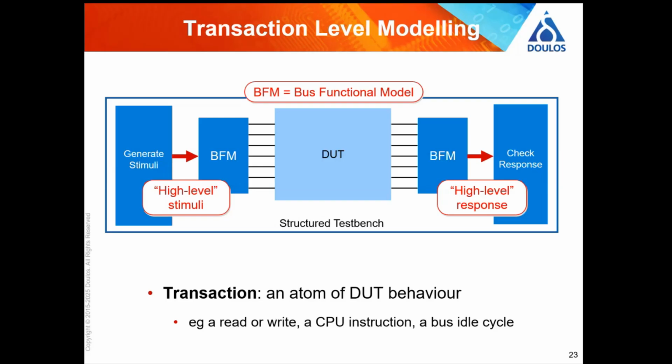And that thing is often generically called a BFM, a bus functional model. And there are different kinds, and I like the terms driver and monitor. So the one on the left of this diagram, you might call a driver. It's translating the abstract transaction, the concept of a write and a read, to the actual ones and zeros that does a write and a read.